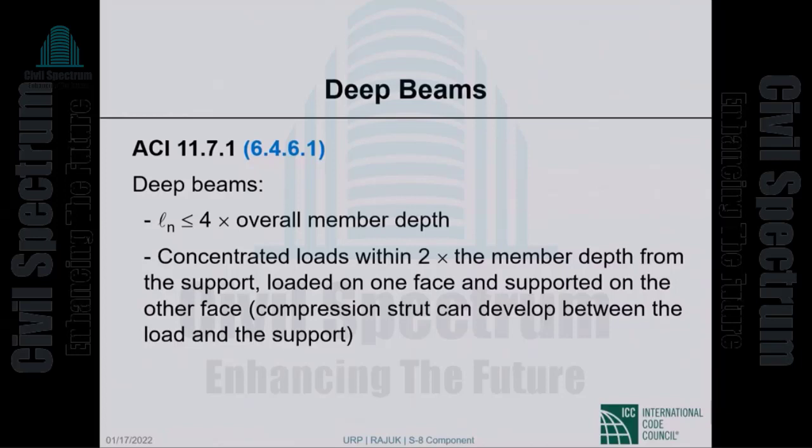So I started from strength of materials, as you saw, trying to make the point that we are designing for diagonal tension, and then the concrete contribution to shear strength, the contribution of the shear reinforcement to shear strength.